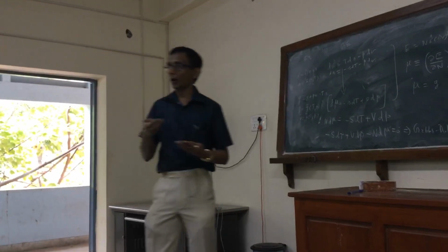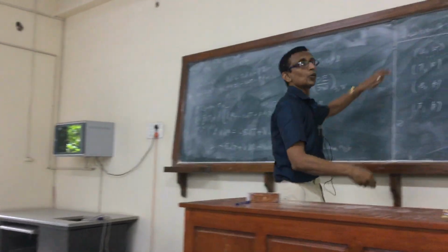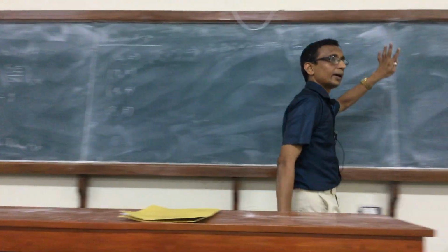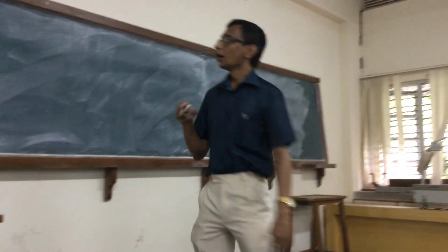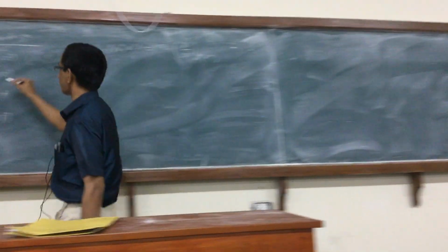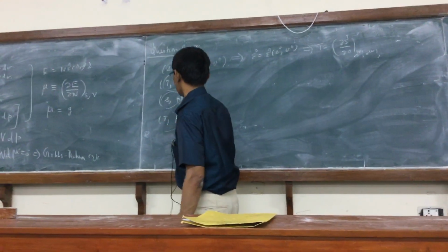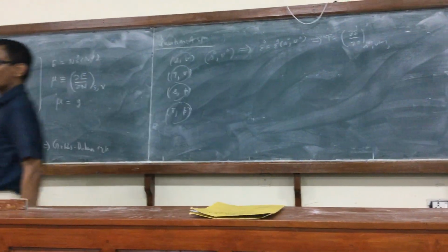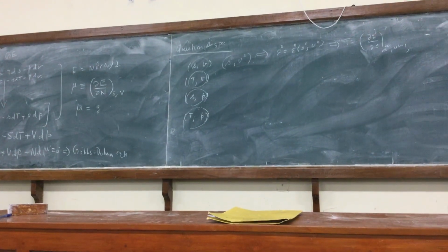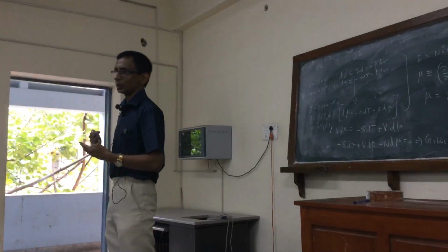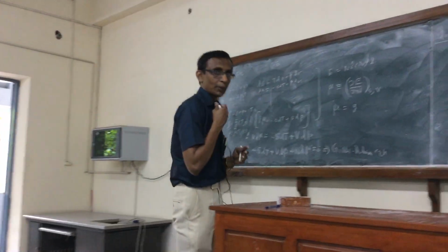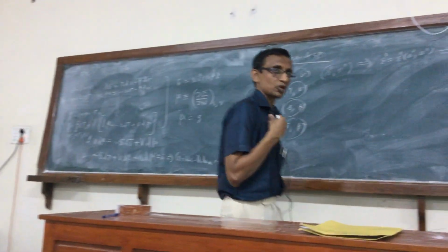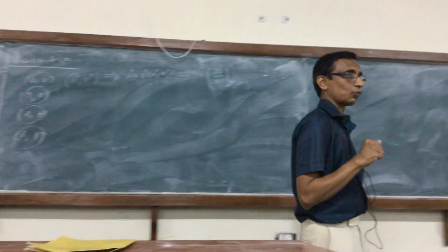So all properties of a fluid in a homogeneous state can be calculated from the specification of two. Either it can be this, or it can be this, or it can be this, or it can be this. So we have four sets of variables, and I also pointed out a combination such as PV, why it is not commonly chosen. In most cases that also might work, right? But it is generally not chosen because we know that it doesn't work in at least one case.